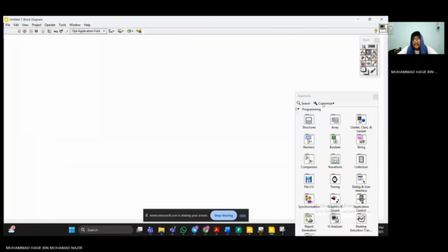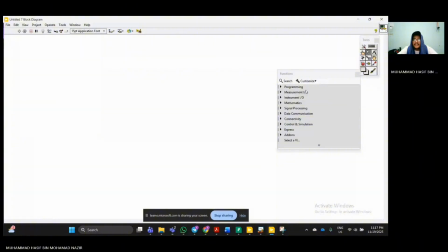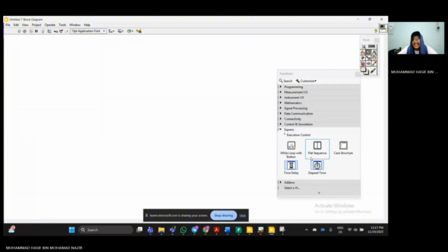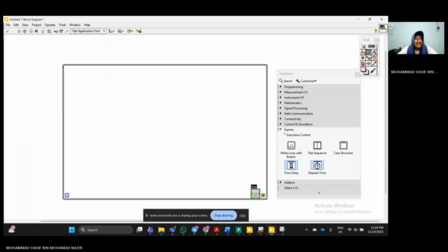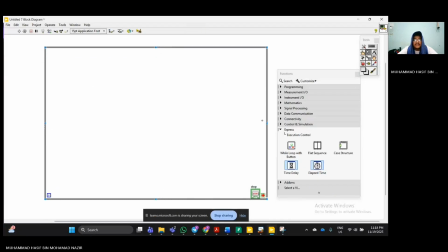For the third task, our focus is to implement a moving average filter in the LabVIEW MathScript node and display the low, high, input and output signals on the front panel graph. Then, it is also to test the filter operation by setting breakpoints and using the MathScript probe to view intermediate variables, S1, S2, input signal and output signal, to verify that high frequency content is attenuated.